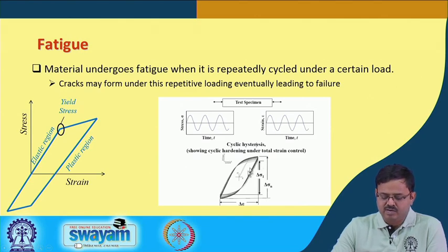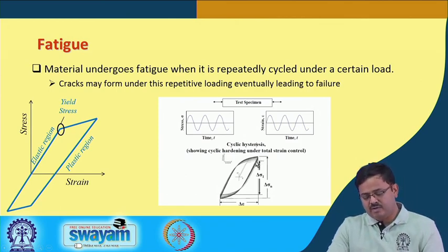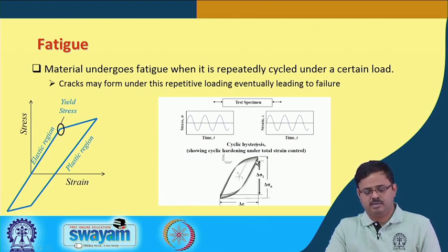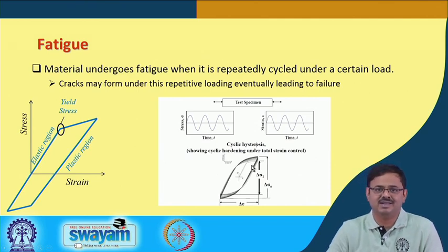But later on, here I started, I went like this, I came down. In the next cycle, as I increase the number of cycles, you can see for the given strain the stress goes up, and also for a given stress the strain goes up. So, this is fatigue, right.